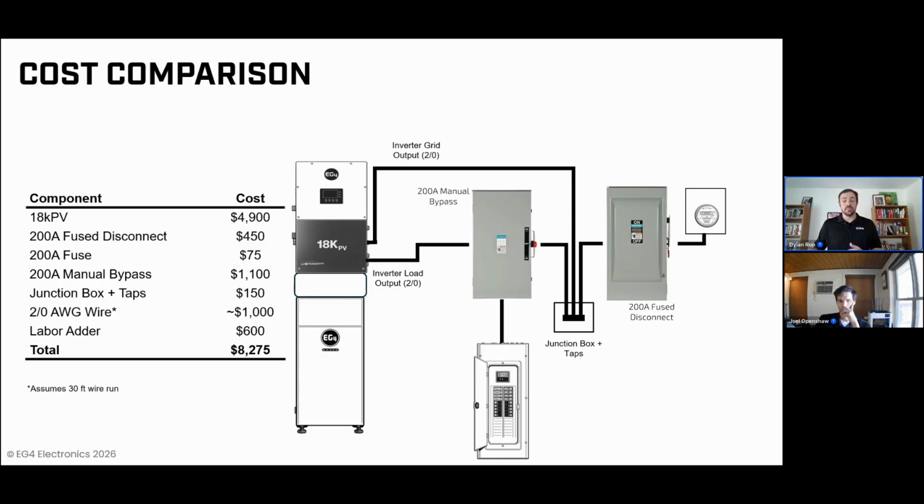And since we're running it both on that line and load side of the inverter, we essentially have to run 3 conductors the length of our run and do it twice, right? Once for the line side, once for the load side. So 3 conductors, L1, L2, neutral, once for line, once for load, essentially 6 times.